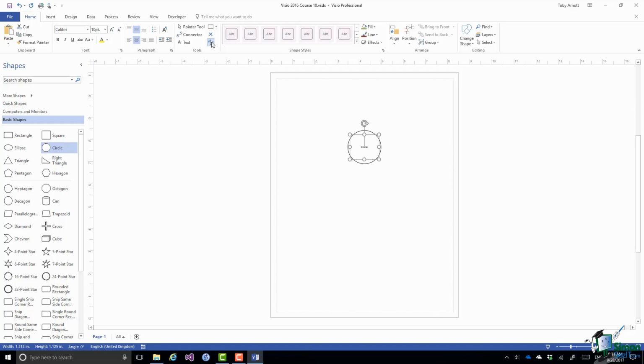The difference is that what I'm looking at here is the text block. And as you see, the text block in this case for this circle is nearly as big as the circle itself, and the text circle is right in the middle of it. As we're going to see in this section, I can do things like change the size of the text. I can even change the size and shape of the text block. So for instance, if I wanted the word in this circle to appear not in the middle but towards the top of the circle, I could either change the alignment, I'll show you how to do that a bit later on, or I could even reshape the text block itself.